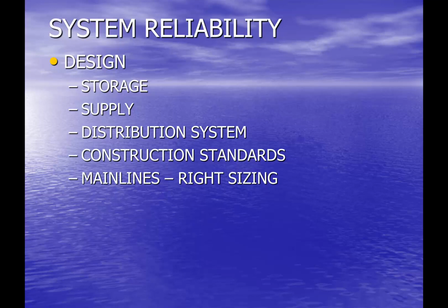The hydraulic evaluation of the system itself, making sure that the system demands are not exceeding the capacity for which the system was originally designed. As that starts to happen, you impact the ability to maintain adequate pressure and flow and may require upgrades of the system.